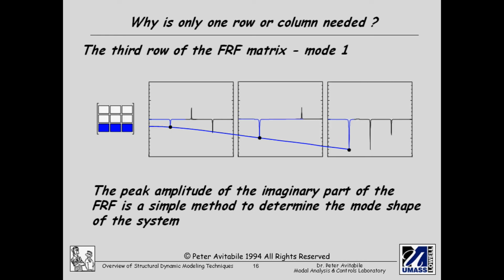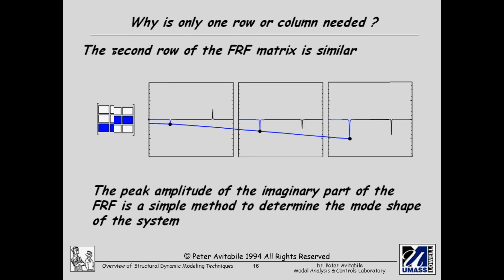You see that these measurements were larger when the amplitude was measured at point 3 than they are at point 2. So that tells me that somehow the location of the accelerometer that I use as a reference to measure these measurements is possibly very important to the total response of the system.